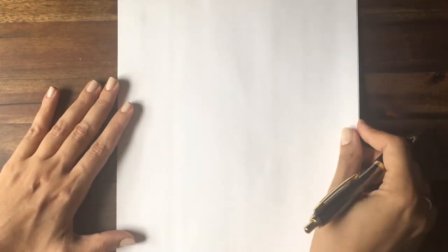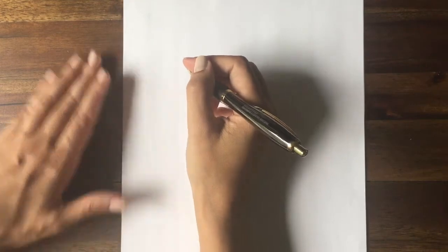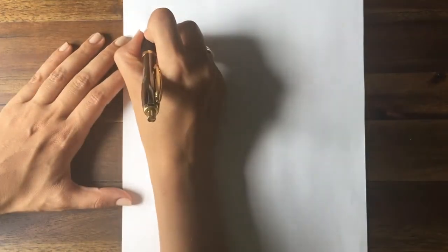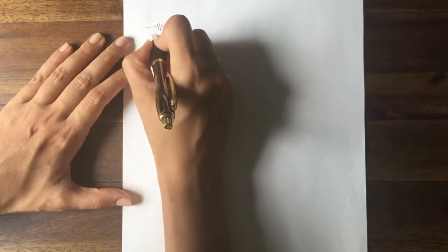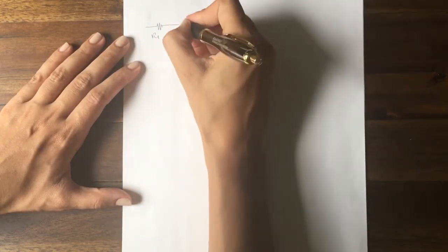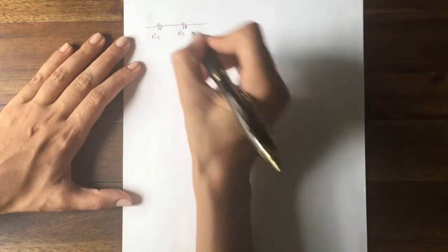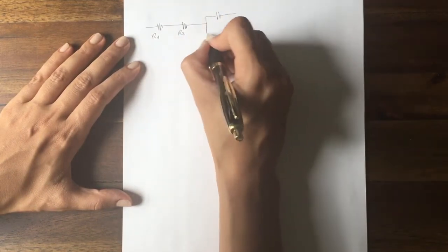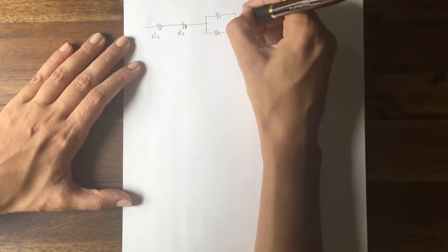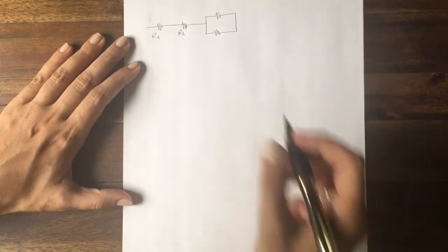We are going to be using the electrical circuit analogy as well here to calculate the heat rate. And if we draw a diagram of the different thermal resistances, it would be the resistance due to the convection in the water side, resistance due to conduction through the plane wall, and then we have a combination of the different thermal resistances due to the fin.